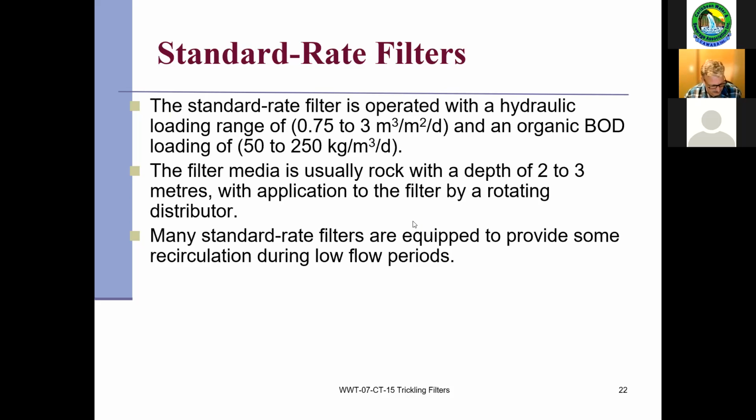Same kind of concept if you have equalization tanks in your systems. It's the same idea. You bleed off a little bit of flow on the higher flow rates into an EQ tank, and then you slowly bleed some of that flow back in to continually feed your biomass. You want to keep your biomass alive and healthy so they can handle the higher flows when that diurnal flow picks up.